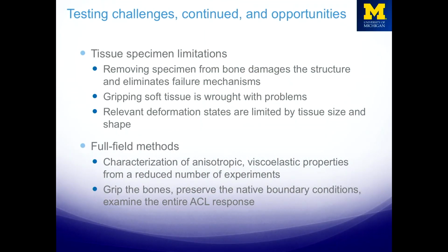And directly gripping soft tissue is a nightmare. It's a mess. It's really soft. It tears. Localization at the grips, tearing at the grips, slipping out of the grips are all issues we have to deal with. So we've been exploring the use of full field methods to be able to characterize these tissues with a limited set of experiments.